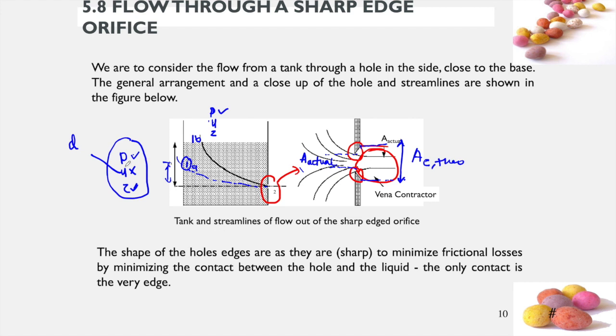Okay, U1 and U2. You may solve this equation by applying the continuity equation. But wait, in the continuity equation, we have U1A1 equal to U2A2. So what is the area 1? So you cannot solve it. U1 will remain unknown. Therefore, you cannot choose point 1A. Okay? Point 1A cannot be used.